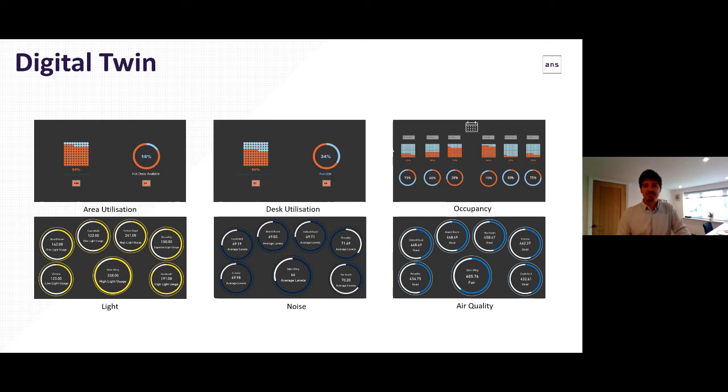That can automatically kick off a ventilator or even just a simple email workflow to open windows or whatever. But it's surprising just in a general office space how much CO2 develops over the course of a day. It drops back to pretty much zero overnight and then takes to about 10, 11 o'clock in the morning when you've got a couple of hundred people in there and you can see it on the monitors. Yeah, it showed it straight away, and same with Bruntwood as well. And straight away we started this with let's get facilities out there, as you say, opening windows or turning air conditioning units on or pumping more better quality air in there.